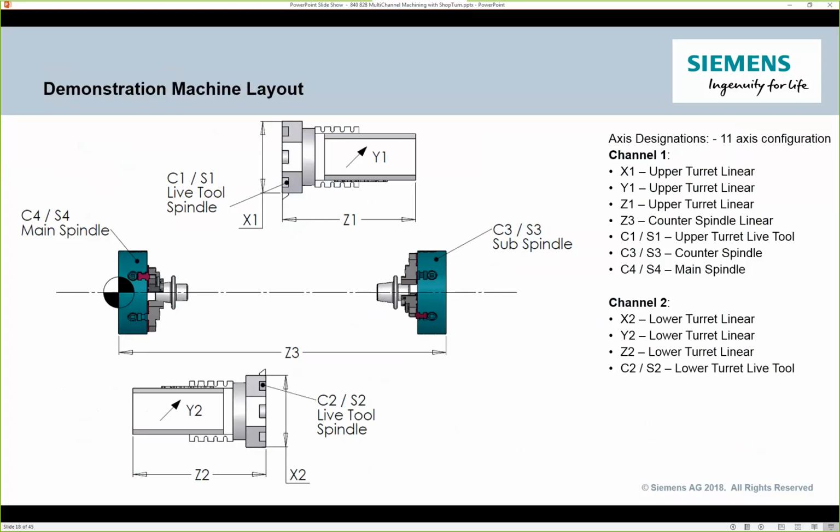Now, if you buy a machine from them and it only has one turret, well, that's going to be referred to as S1. My sub spindle is always S3, main spindle is always S4. So it's kind of like a T, right? You're making almost like the sign of the cross, a little bit inverted: upper, lower, sub spindle, main spindle. So maybe you buy a very simple main spindle and one single turret machine from DMG. Well, they're going to call their main spindle always S4. This way they have consistency in the product.